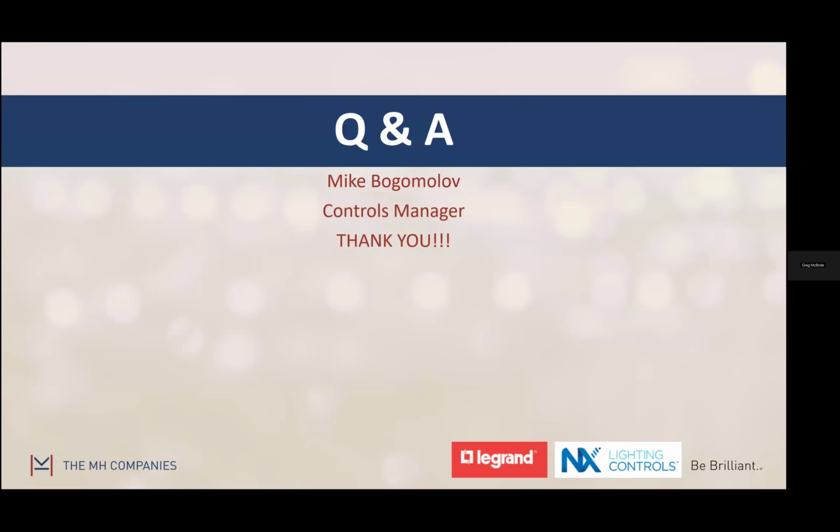So the first question is, does decorative lighting count for daylight zone wattage calculation? Okay, if you have decorative lighting inside of your daylight zones, unless it's a specific application sort of lighting, like maybe you have a pool table near a window with light fixtures over it, technically I would consider that special application lighting. So in that case, no, you probably won't have to do that. However, if that decorative lighting is being used as part of your general lighting in the space, yes, you do have to take that into consideration.